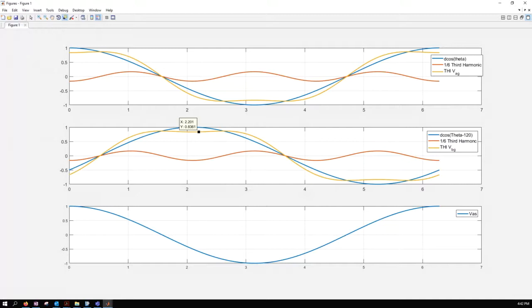Okay, so that means you can get more voltage in, and you can go to a higher speed or provide a little bit more current to get improved performance from your drive stage. Okay, so there is an advantage in doing third harmonic injection because now you can reach slightly higher phase voltages. Okay, now in practice, of course, you can inject third harmonic component like we just did, right?